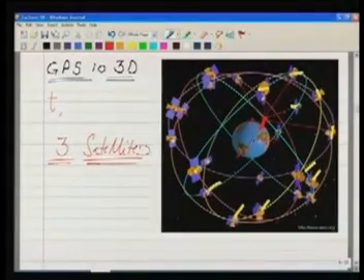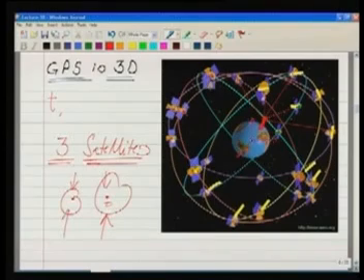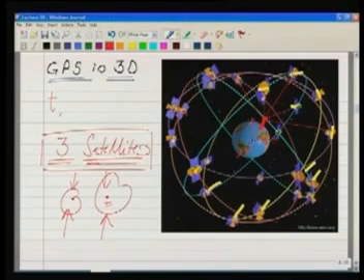Now, in order to fix the point, what we do, we take the third satellite. So, again we have got one more sphere. So, this third sphere will cut this circle in 2 points. So, basically if we are using 3 satellites, finally we end up with 2 points which are our solution points, and one of these points will be not a practical solution for us, because from the domain knowledge we know this point has to be accurate. So, basically by taking this into account, it is possible that by 3 satellites we can determine our position.